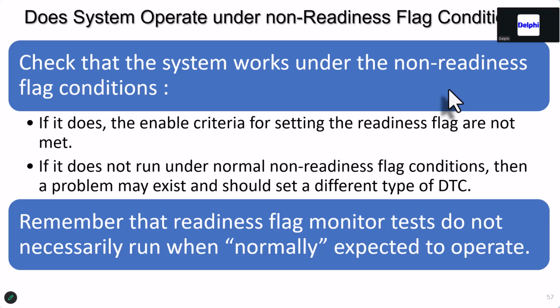Okay? And flow. EGR, purge. You get in your driver's seat. You're wondering if the purge works. You rev it up to 2,000 RPM in your front seat. You look at your scanner. The purge opens up. The FTP drops. You know the purge opened. You know you met the criteria to open the purge.